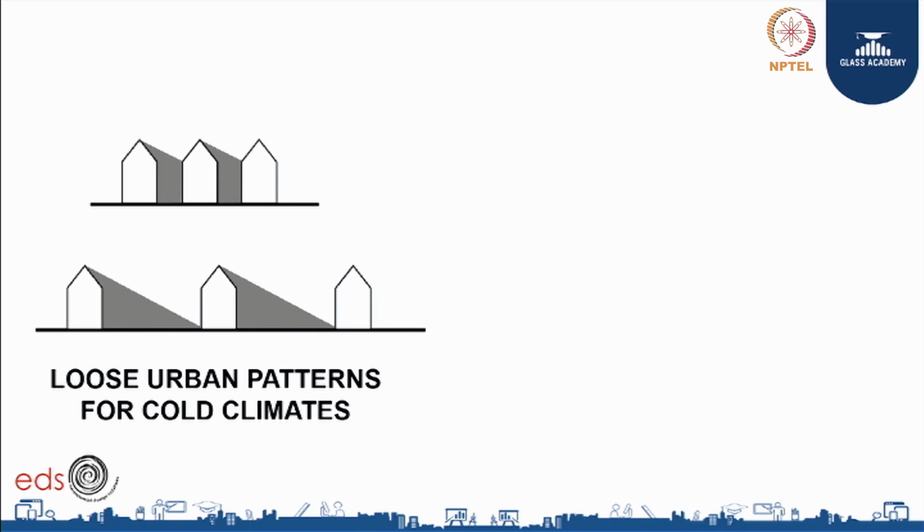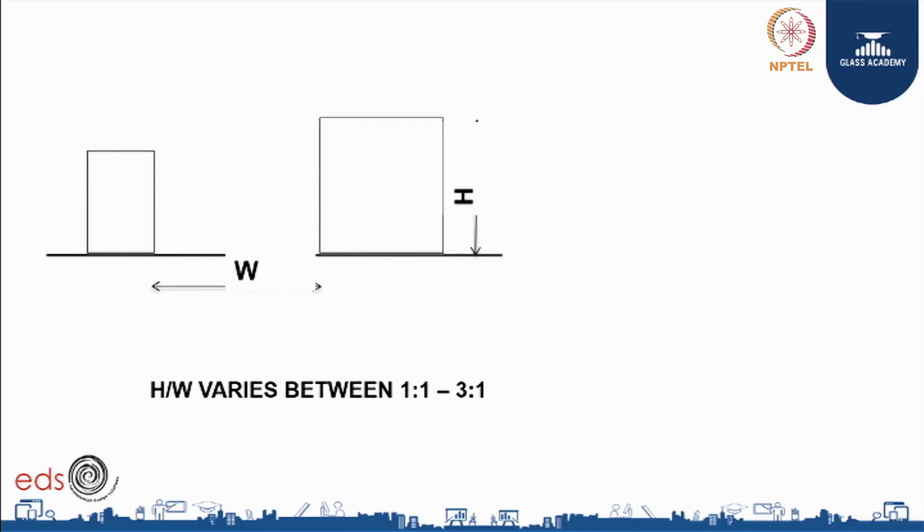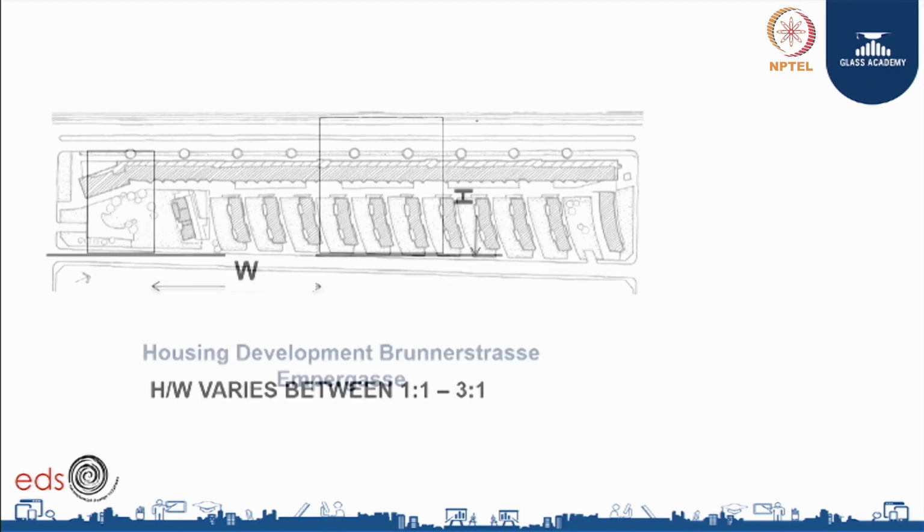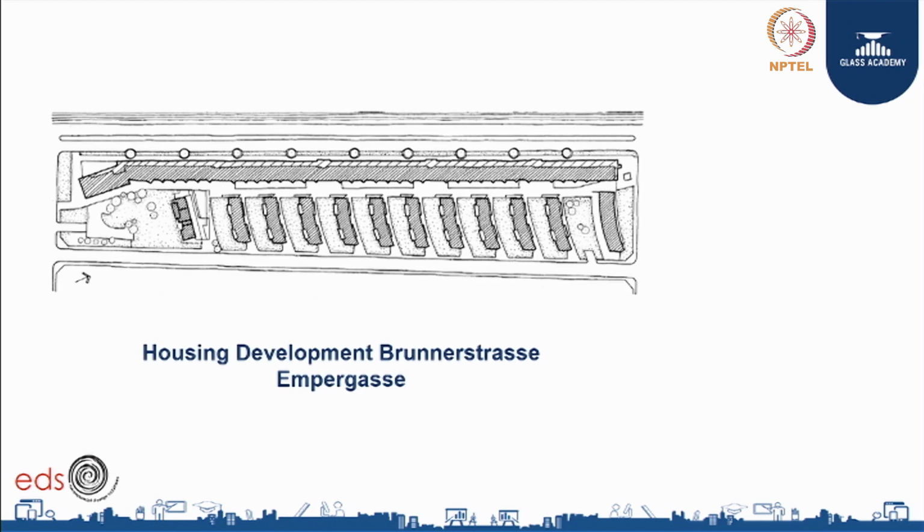There are many ways to determine the street widths for given building height or vice versa. Though in most cases, the building height to street width ratio varies between 1:1 to 3:1 depending upon the climate and density of the site. Try to keep taller buildings towards east or west so that they cut off the harsh glare from smaller buildings. Also try to house facilities like storage and services in these buildings.